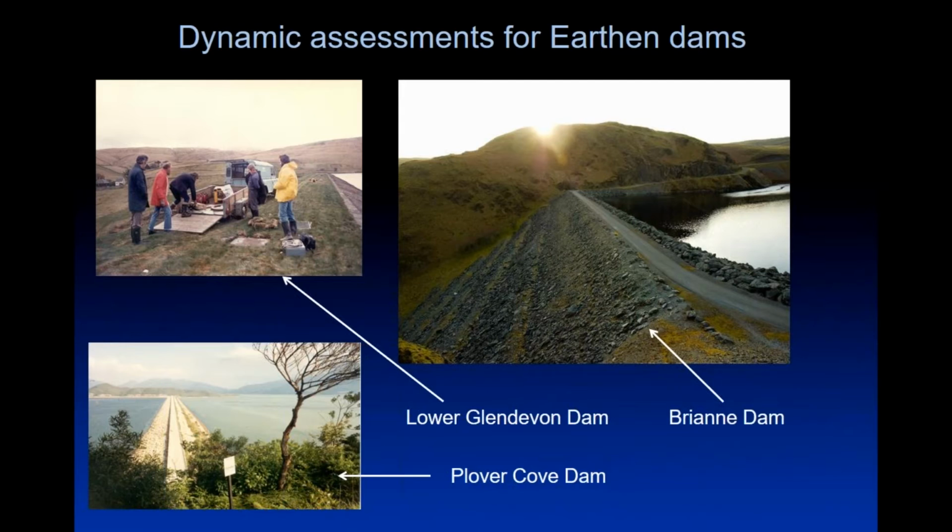Nowadays, we don't need to shake our structures because we've got the calibration from these induced vibration tests. We know what normal behavior is from this. So earthen dams, yes, they're fine. Clay core, large amount of berms down here. We've got top left, Lower Glendevon Dam in Scotland.